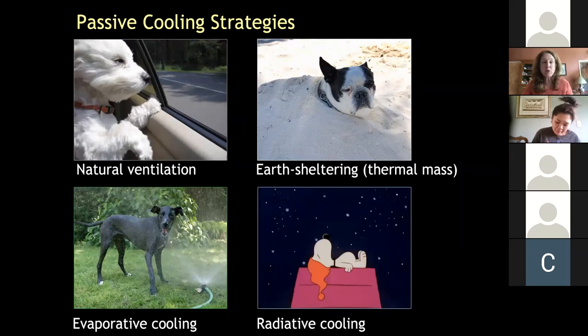That's where you're removing heat from your body to the air, from the space to the air. Natural ventilation has lots of different ways of providing cooling. We talk about bodily cooling, where you're trying to make yourself comfortable by removing heat, and also spatial cooling, where you're trying to remove heat from the space itself.